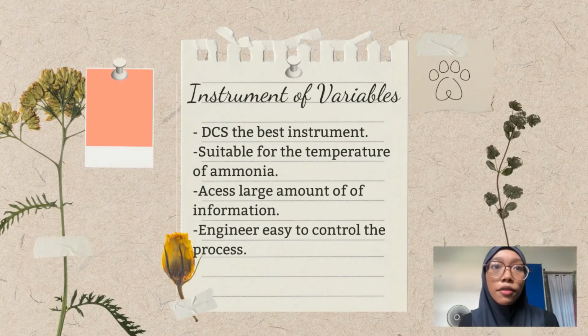After have a feedback from the another authors, the best instrument is DCS because specially designed control system used to control complex, large and geographically distributed applications in industrial processes. It also connected to both field devices and operating PCs through high-speed communication networks. Discrete field devices such as sensors and actuators are directly connected to input and output controller modules through communication bus.